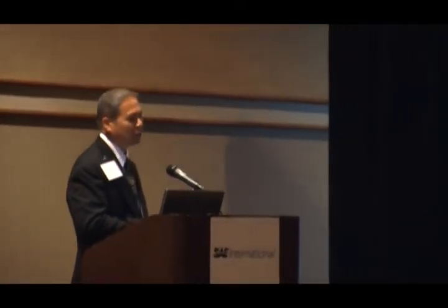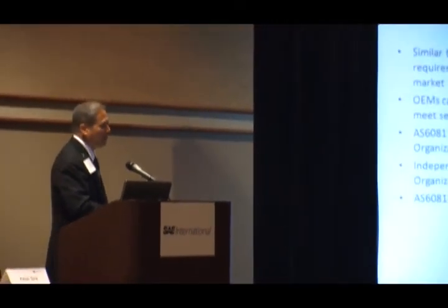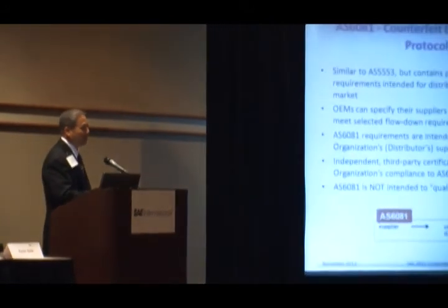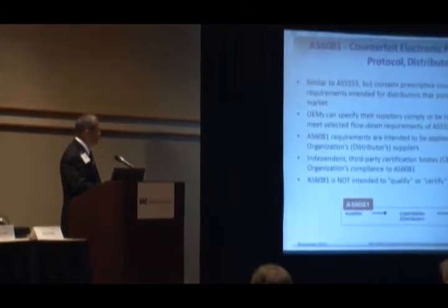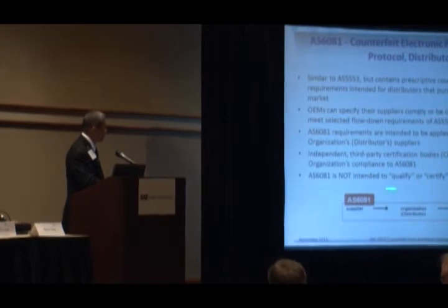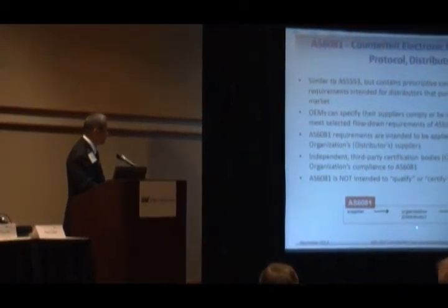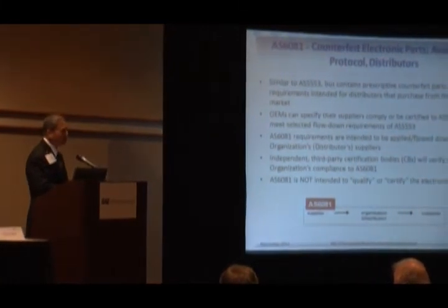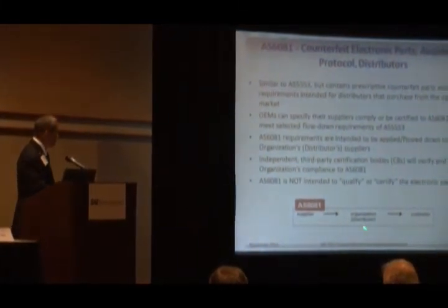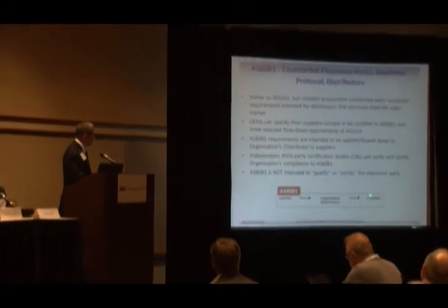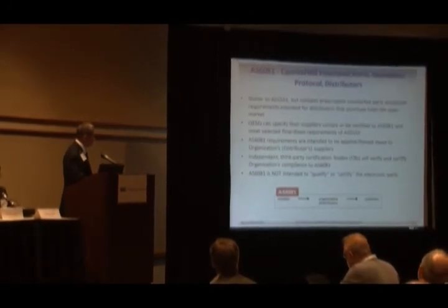One of the things I wanted to point out with this last bullet is that we started to hear the term AS 6081 qualified parts. I want to make sure that everybody knows that this document is not intended to certify or qualify the parts. This document is intended to certify the distributor of those open market parts.